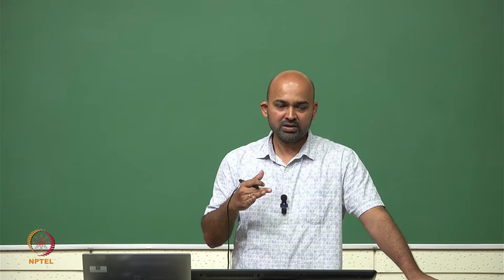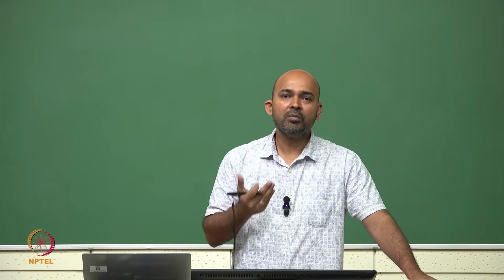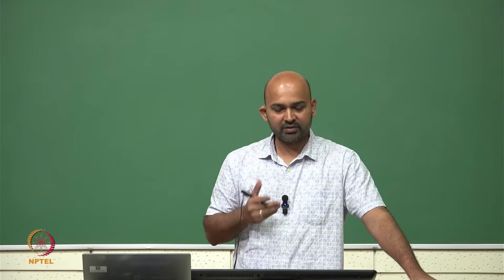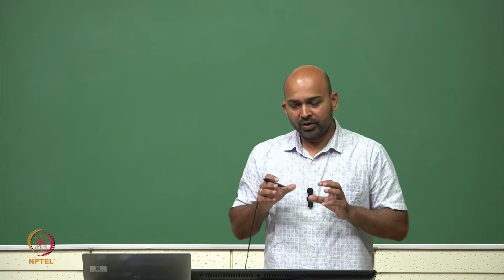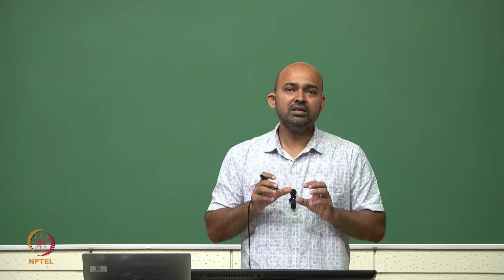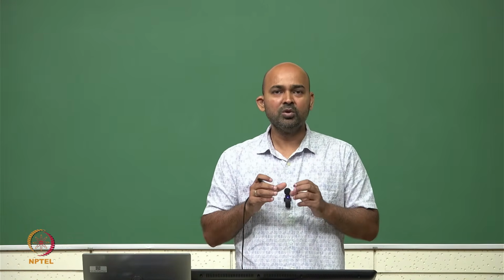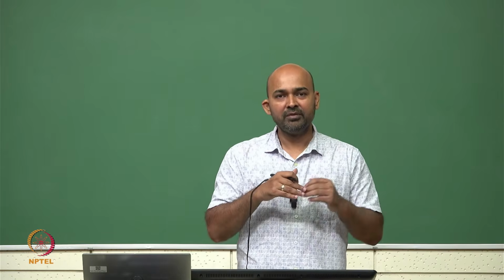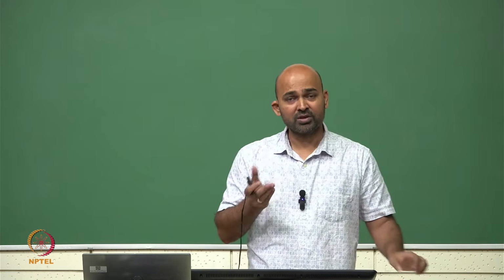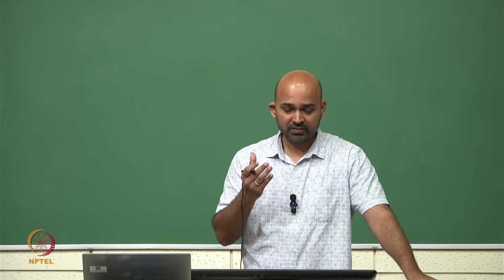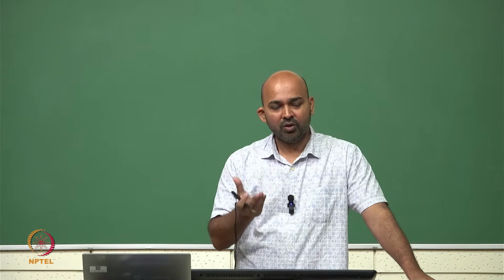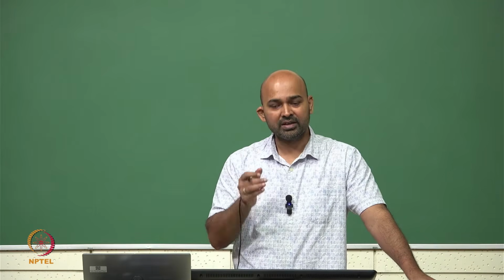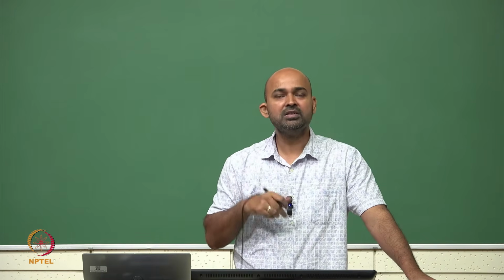How does SPICE perform the DC operating point simulation? That we need to know. For a DC simulation, first we need to know there are circuit elements which behave differently at DC and in the transient simulation. For example, our capacitor. We all know that the capacitor for DC is an open circuit. There is no current flowing for a DC voltage.